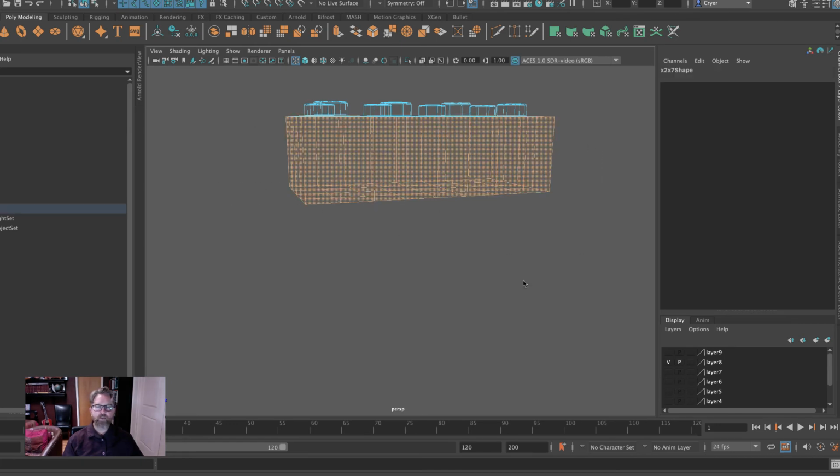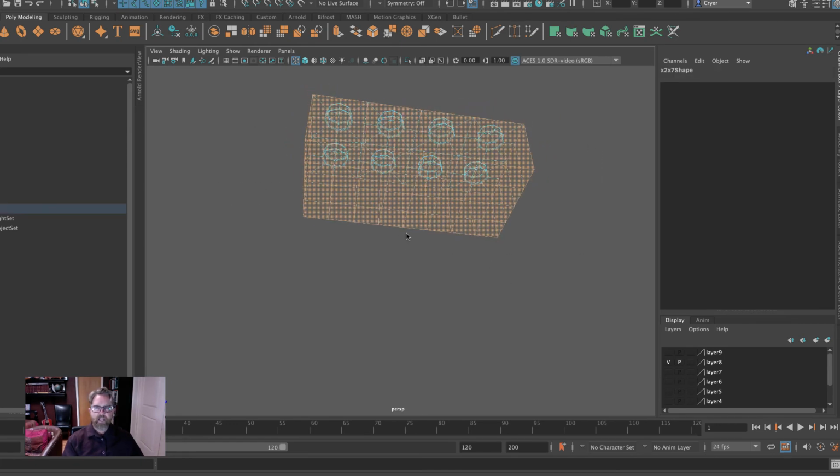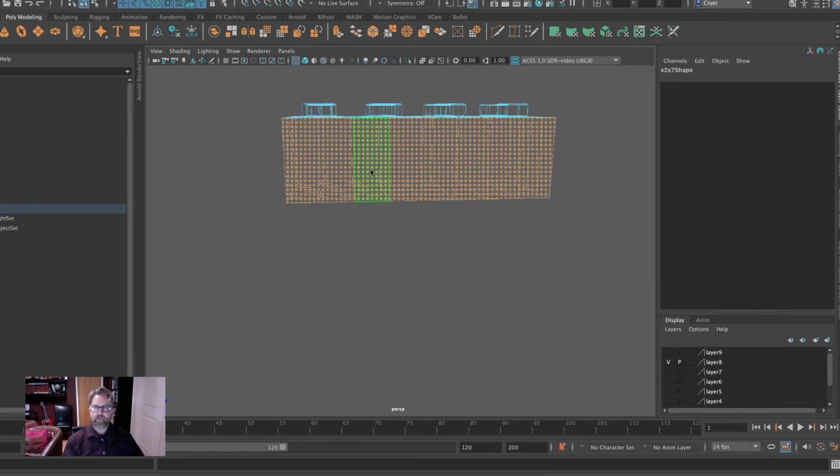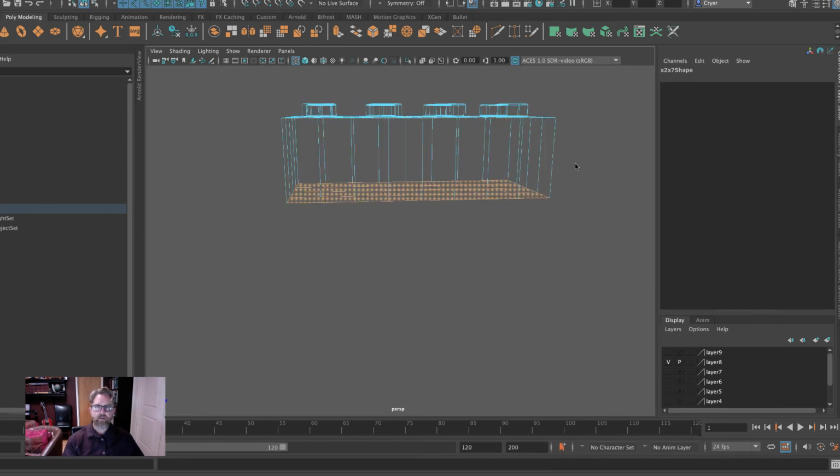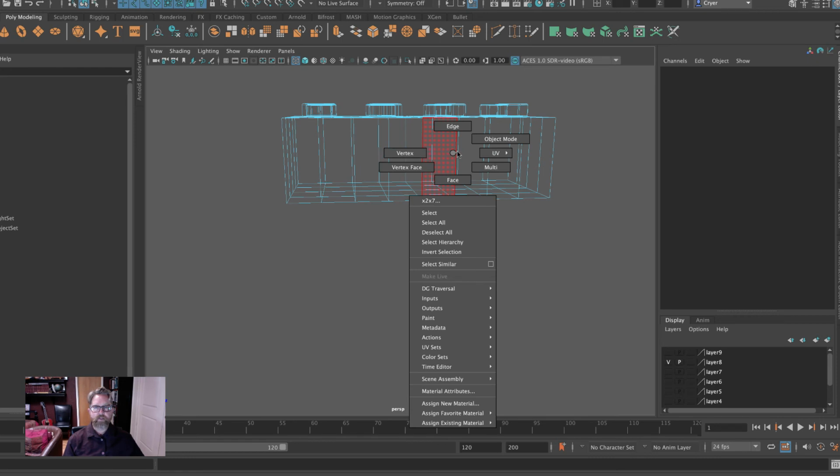You say, well, we don't want those. But grabbing everything gave you all the bottoms, and then we can just use that Control key of deselecting. So that was much quicker than doing the shift double click. But in some instances, if you only have a few faces and it's an odd angle, the shift double click may work. But for this nice clean scene,